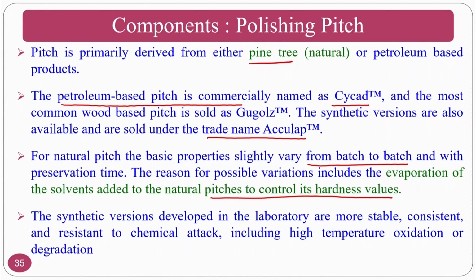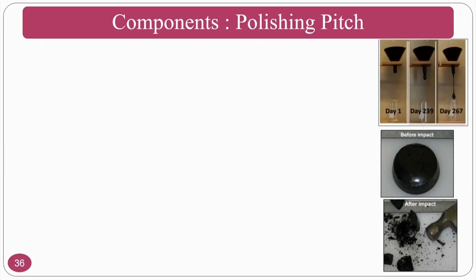The synthetic versions developed in the laboratory are more consistent because the synthetic ones are developed as per your requirement. I know this much elastic component is required, I know this much viscous component is required, so that you can develop your own. But with naturally available pitch, you have to take the properties that it has, and the only thing you can do is use some solvents to modify it, that's all. You cannot decide the properties that you require. These are the polishing pitches.